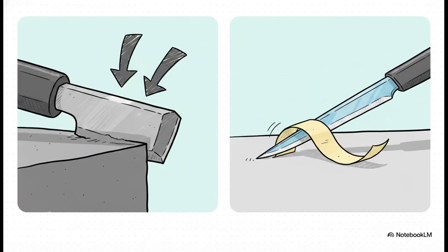So, the crucial point here is that your tooling geometry absolutely must perfectly match your material's hardness. Hard materials demand a strong, honed, or T-land edge preparation just to survive all that immense pressure. Conversely, softer, more ductile materials require a dead sharp edge with a high positive rake angle. They basically need a razor to cleanly slice right through the material without just smearing it across the surface.